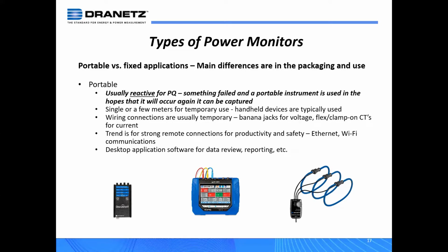The purpose in analyzing it is basically to determine what mitigation I need to apply to correct the problem. So when you look at the difference between the two, you have a PQ detector, data logger, versus a little bit more advanced unit that performs all the functions that a data logger and PQ detector do, but also has the ability to allow you to analyze data as well.